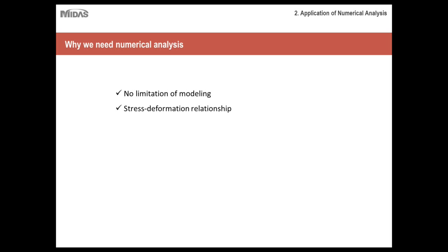Okay, the stress deformation relationship. So soil element stresses as well as structural stresses and deformations can be analyzed in detail with numerical modeling. This becomes more and more prevalent for certain projects where you would need to, for example, calculate the displacement, for example, settlement type projects, retaining wall projects for deep excavations, etc.